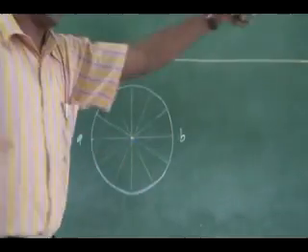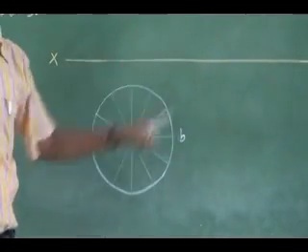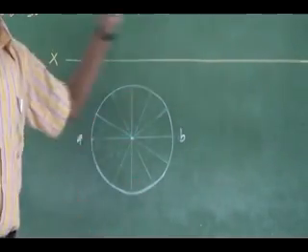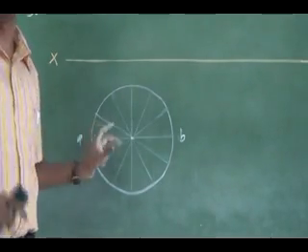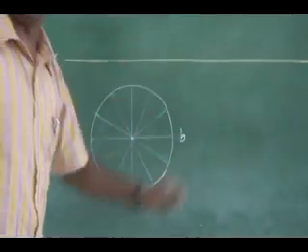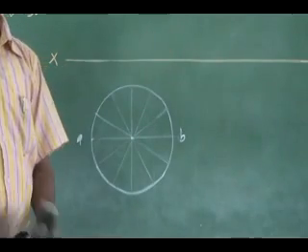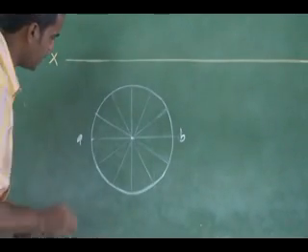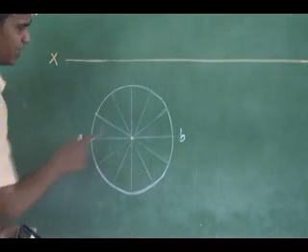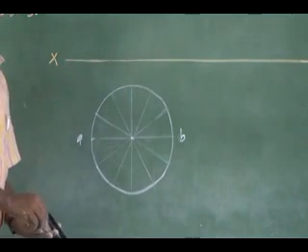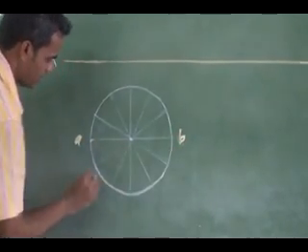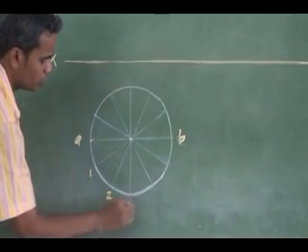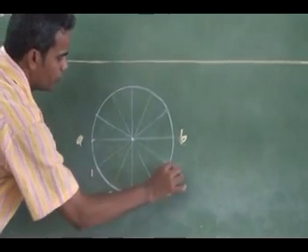See here, for pentagon, polygons you have corners. Here I don't have corners, I have infinite corners. So I am dividing and getting a finite 12 corners here. From that finite 12 points, I can get my final front view and top view. So this is my A, B. Other things I can give in notations. In numbers I can notate it if you want. This is 1, 2, 3, 4.